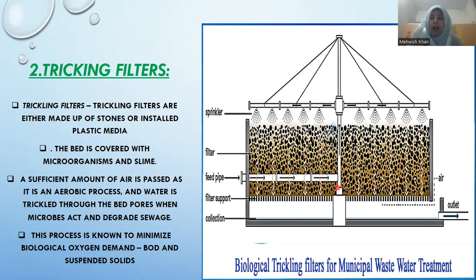Well, one more point I want to add here is that the tower should be continuously moist. If it becomes dry, what will happen? The microorganisms will not function appropriately, and they will even die as well. So this is all about the trickling filter, and the next.